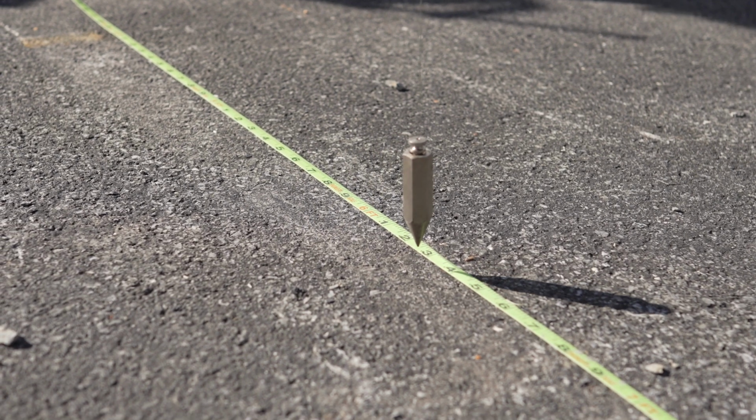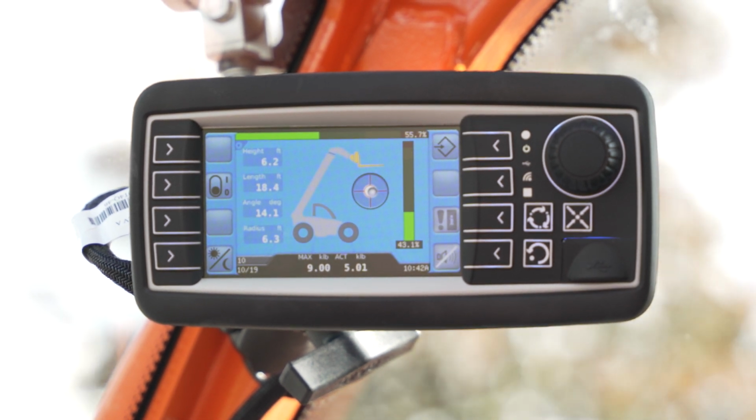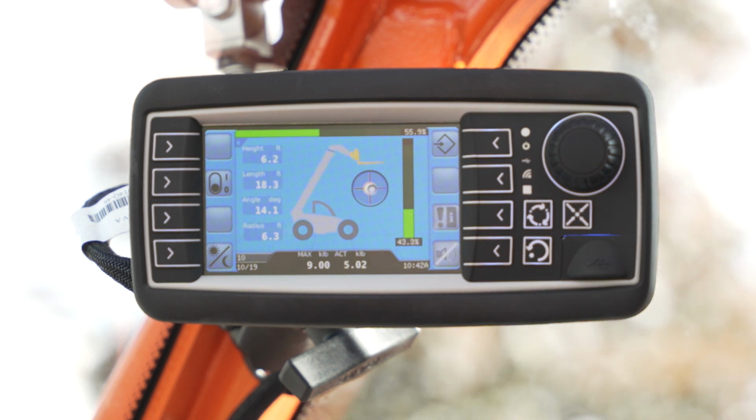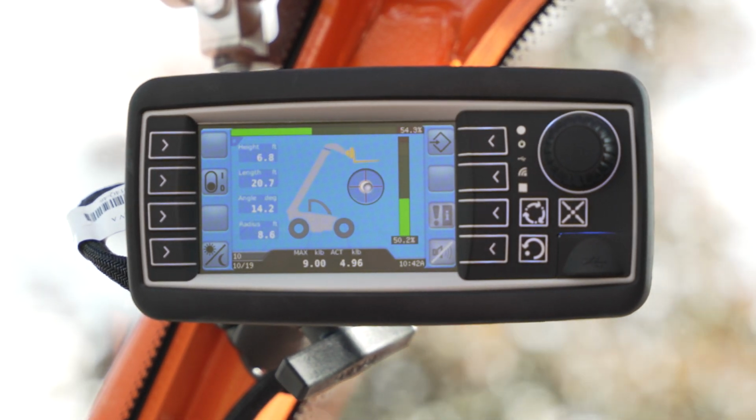Compare your physical radius measurement against the value displayed on the console at 3 different length and angle combinations. It's important to note that the radius is displayed in feet. The numbers after the decimal point are tenths of a foot, not inches. After confirming the radius calculation is accurate, you are now ready to begin the static and dynamic measurement process.